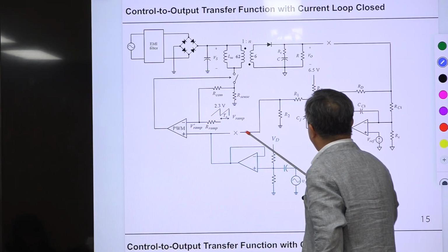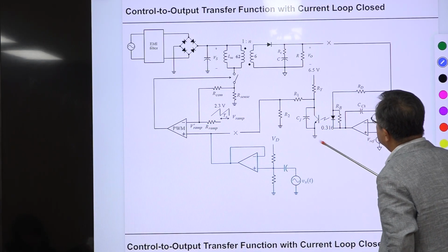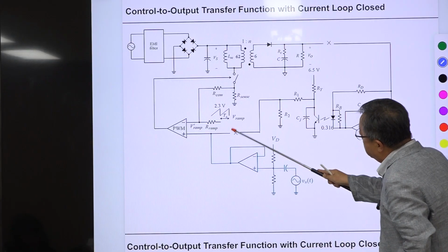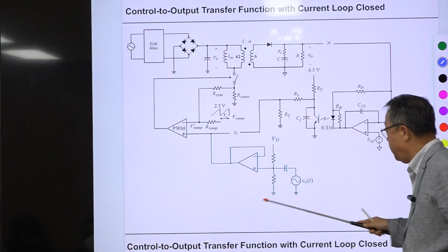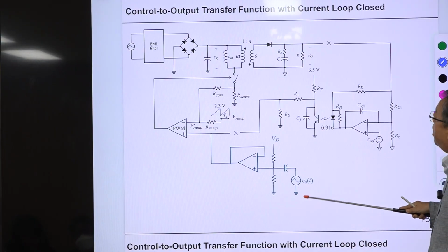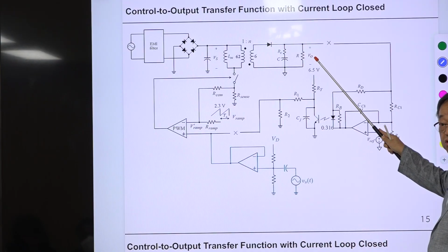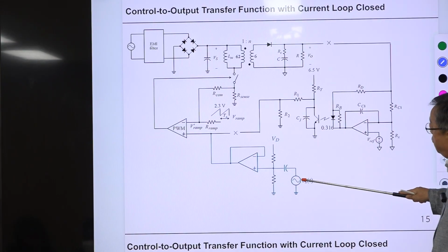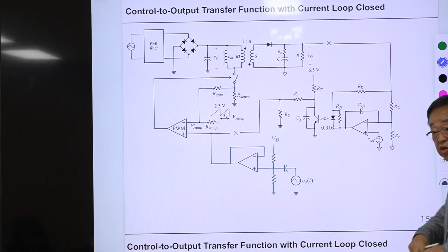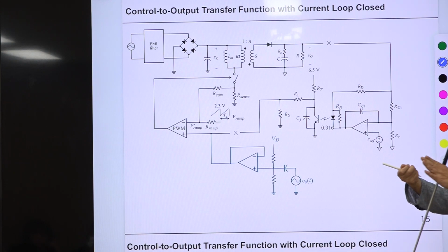So this is the voltage feedback compensation part, right? And you cut here, then you add this. Then you excite this and measure this using your equipment. That is the measurement. You excite this with your simulator with the sinusoidal wave while sweeping the frequency of the sinusoidal waveform.